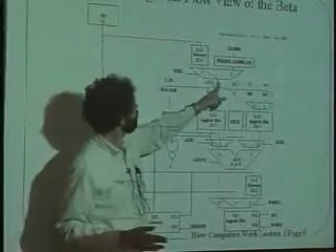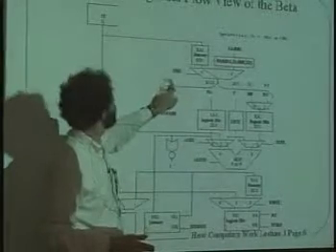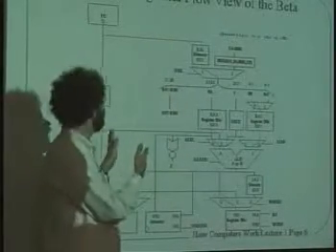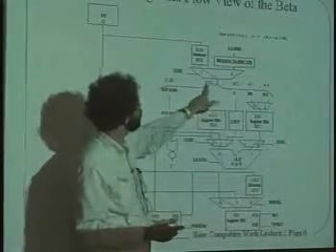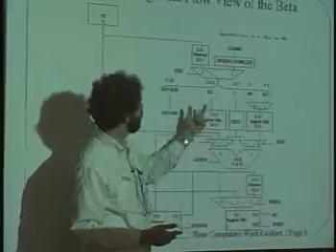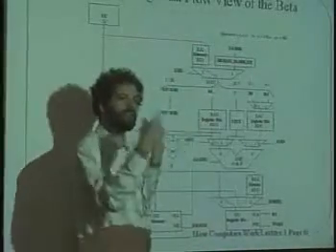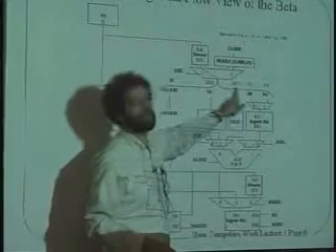Well, it takes those 32 bits that come out of this particular selector, and it takes the high order 6 bits, bits 26 through 31, and it calls those the opcode. Because if you remember, the left-hand 6 bits of this thing were the opcode. It takes bits 21 through 25, which are the next 5 bits, and says those are register A. So it's just breaking apart this 32-bit word into several fields. It takes bits 5 through 20 and calls that C, the constant.